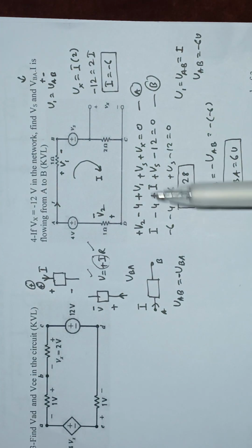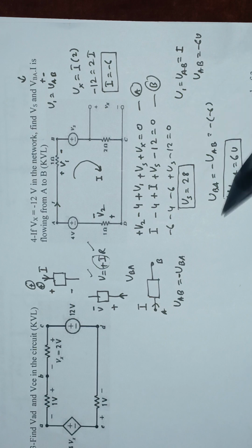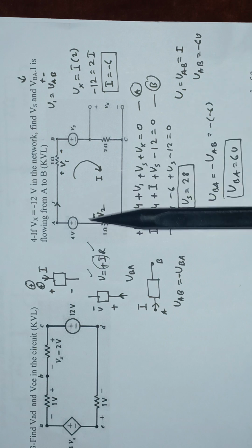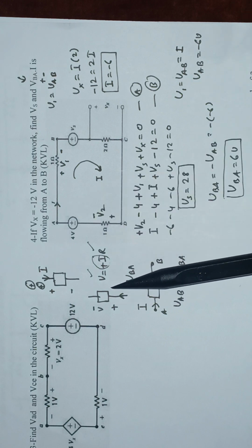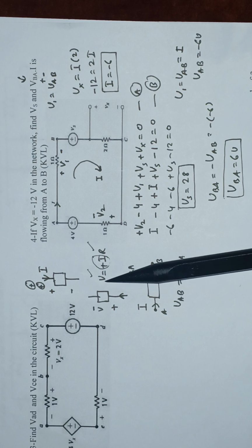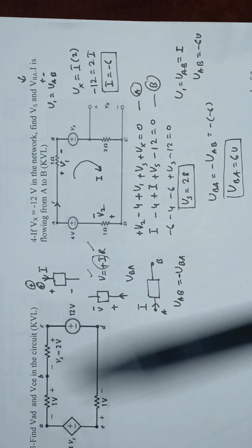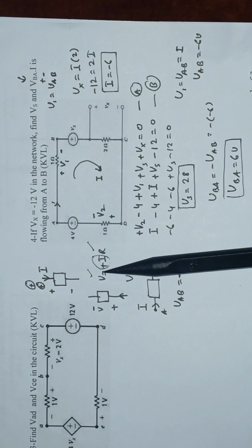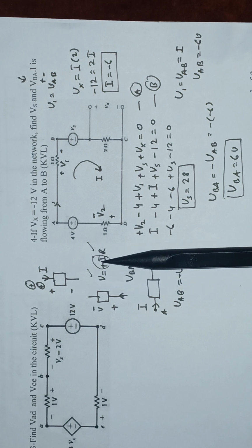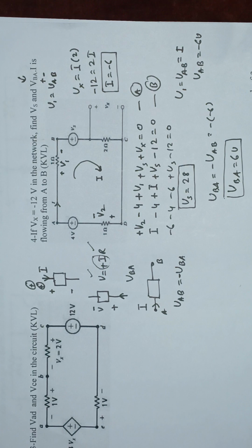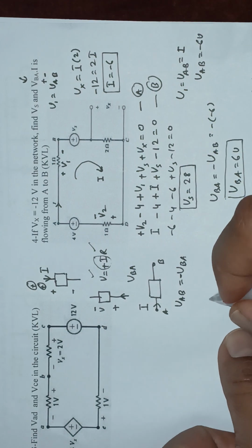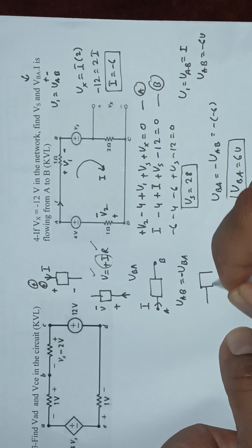So that is how we have to do this problem. The main thing was to know the passive element, how to apply Ohm's law across a passive element, and also the passive sign convention. And the passive sign convention, I will repeat here, is that we cannot assign the current and voltages independently. I will repeat once again.